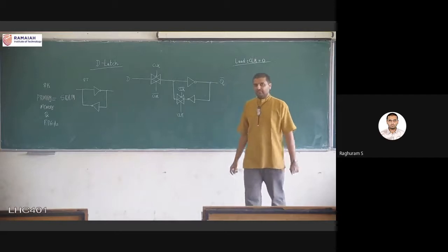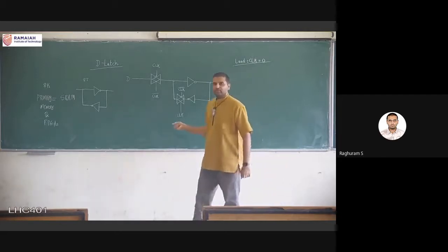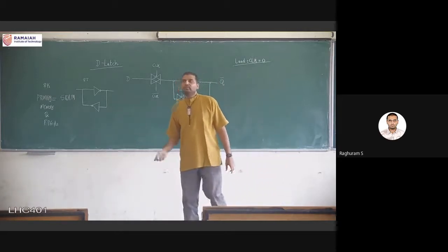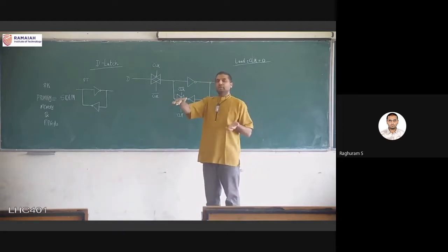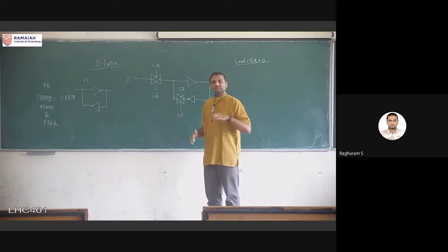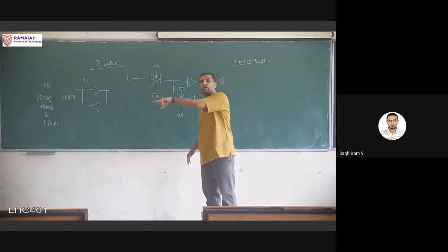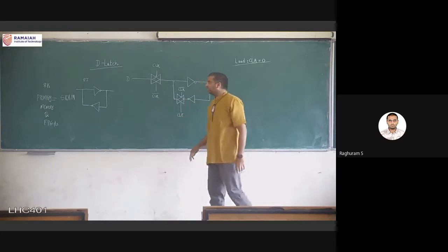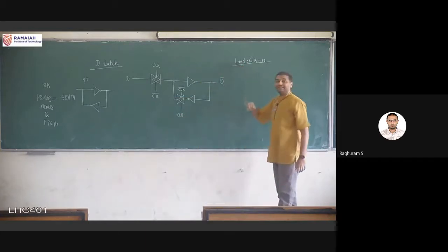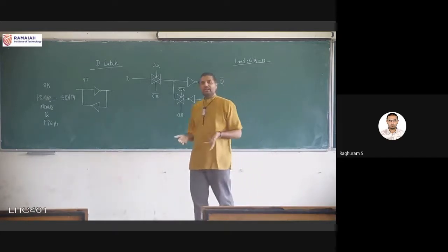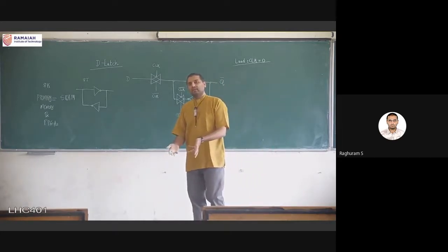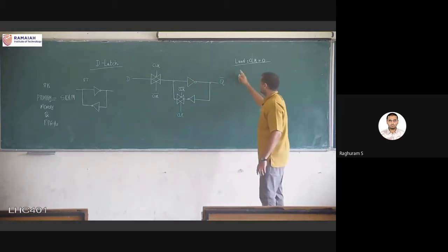Just like the waveforms in the previous diagram, we want to implement a latch that is sensitive to the negative edge of the clock, which means that as long as the clock is low, the data should be continuously going to the output. So I will call that the load phase. Load means load the data into the cell, and this equivalent circuit will be D.